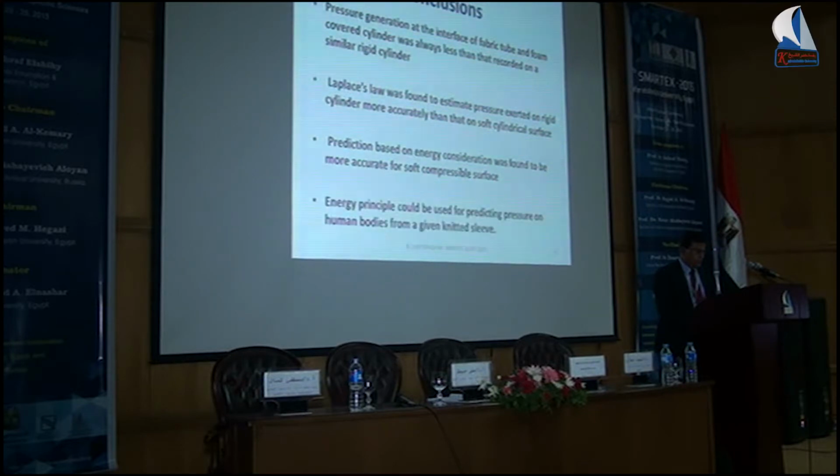So the conclusions are that the pressure generation at the interface of a fabric tube and a foam covered cylinder was always less than that recorded on a similar rigid cylinder when the diameters of the two cylinders are the same. Laplace law was found to estimate the pressure exerted on a rigid cylinder more accurately than that on a soft cylinder surface.